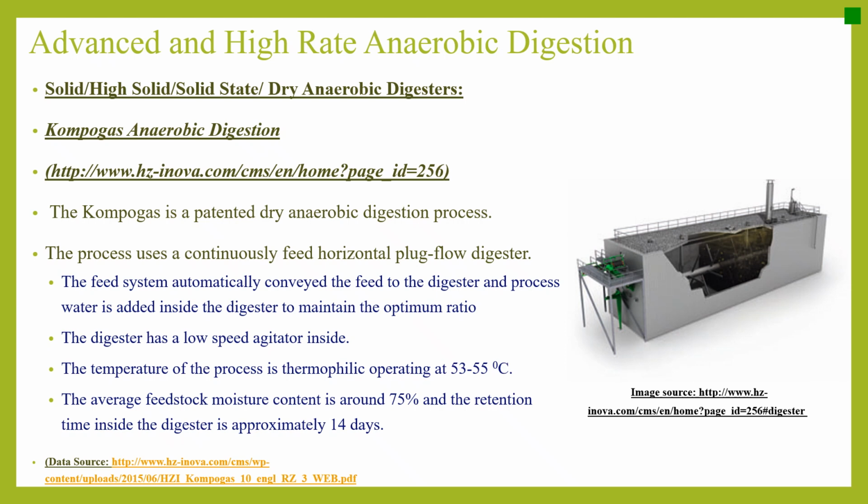The temperature of the process is thermophilic, operating at 53 to 55 degrees centigrade. The average feedstock moisture content is around 75% and the retention time inside the digester is approximately 14 days. So here is an image of the Compogas process.